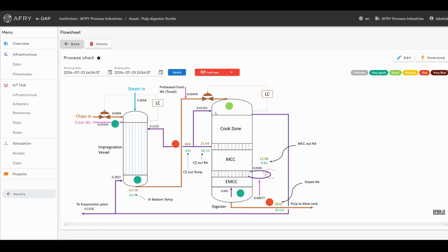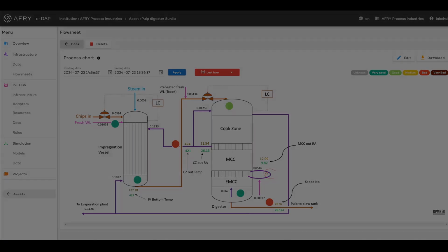The data is collected everywhere from sensors located at specific places. Important to know in this process is that inside the digester itself, a production of the pulp along with other residues happens based on different conditions. The quality of the separation process and time, which normally takes between 3 to 6 hours, is usually quantified by a specific KPI known in the field as the blow kappa number.